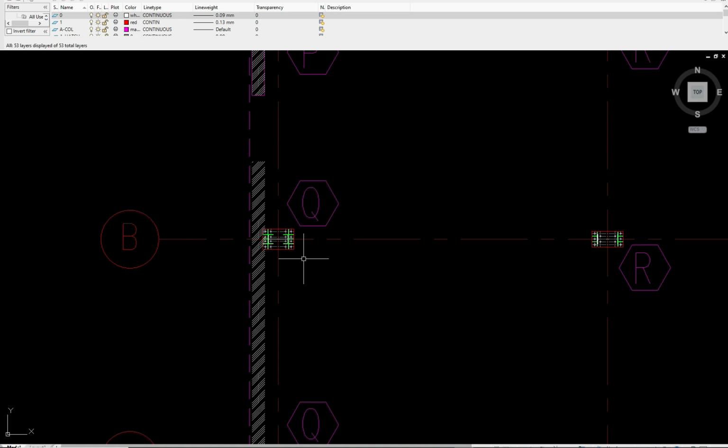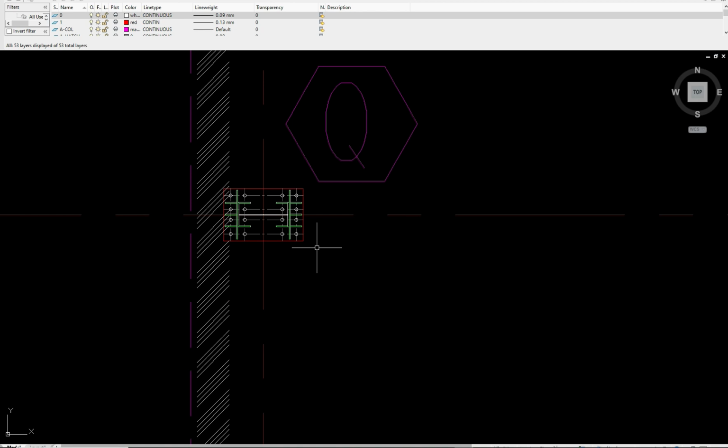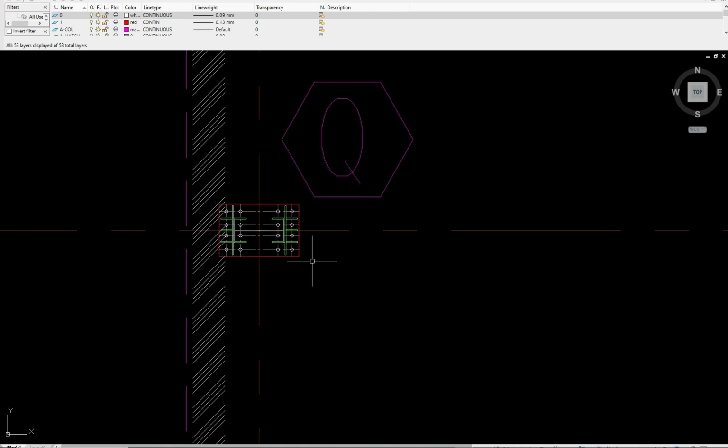They just do it to ease their anchor bolt fixing part, but economy doesn't remain a consideration for them. As a structural engineer, we should not do that. We should always try to provide as economic a solution as possible. So we'll take an offset of 75 mm around this base plate.